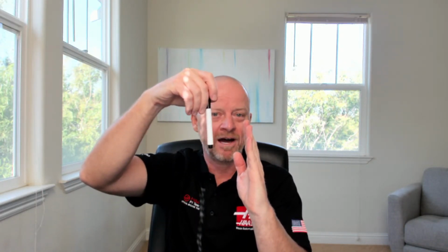So if this is the wall of your part, and the probe is expected to hit, and let's say this is where it's supposed to be, but the operator maybe loaded the part 15 millimeters this way, and it's supposed to hit within 5, but it doesn't, it would just alarm out. Now going back to the other example, if the part is here, and my probe starts here and moves over, and we expect it to come down here, but the operator loads the material more this way, it will come down here, hit, and then back up and alarm out, because it's in protected positioning mode.